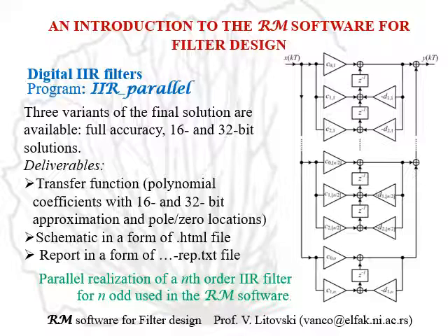The program produces several files as a final solution, which are a report file containing the complete report, all the calculations, including the pole zeros of the untransformed, the transformed filter, and the values of the coefficients, the process of evaluation of the coefficients, and so on, while also it produces a HTML file where, in addition, the schematic may be reconstructed.